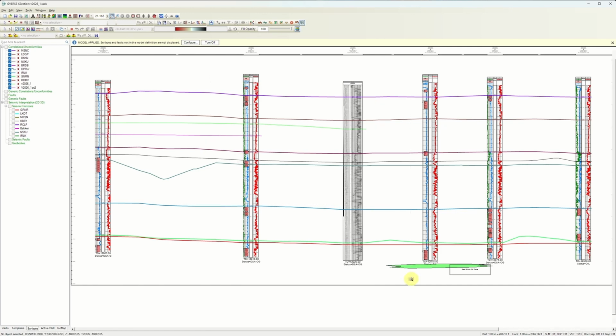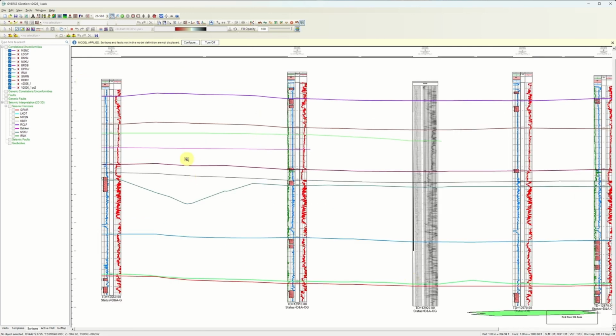One of the biggest features we've done is the ability to have unlimited undos and redos across all different picking modes. Whereas before that was limited exclusively to the quick pick mode, where it would not save your wells to database, thereby giving you the ability to run through and pick different trial points. But now I can come in and turn on my picker mode, and now I have the ability to run different cross lines and inlines. Different picks on my formations, while I can mitigate quick mistakes as well as make different trial points.